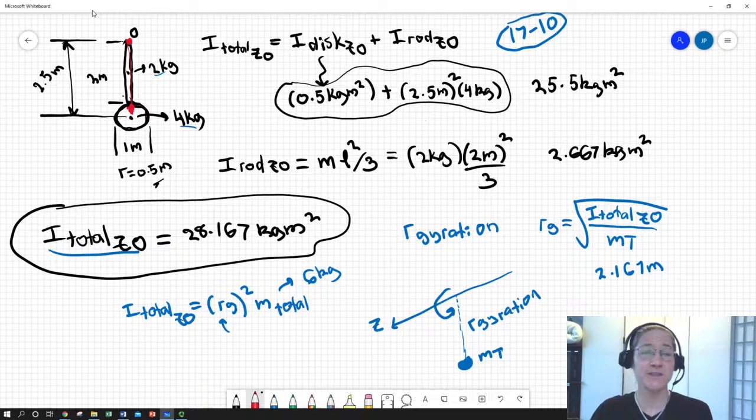A lot of times it'll be the center of mass, especially if you're breaking up rotational and translational components of motion, but other times it'll be about a fixed point that's convenient. So this gave you a lot of tricks to do that so that you know your I in your sum of the moments equals I alpha is going to be correct as you go forward. So that is it for this mini lecture, and subsequent ones will deal with putting this together with other equations of acceleration and kinetics to actually solve some rigid body planar kinetics problems.